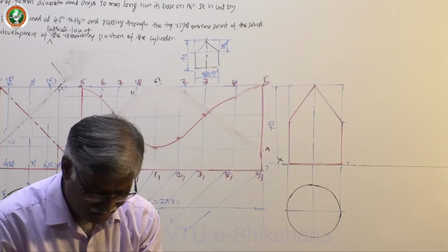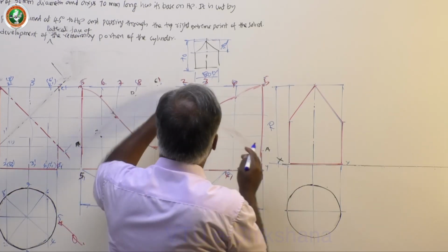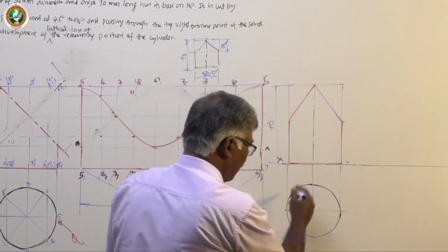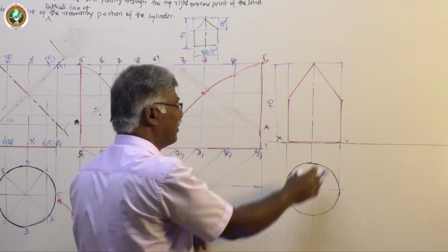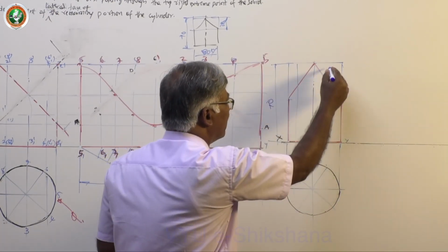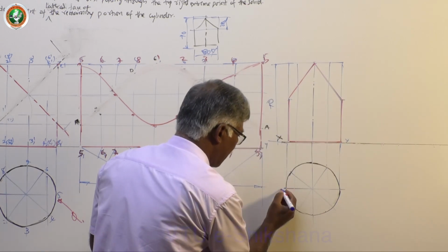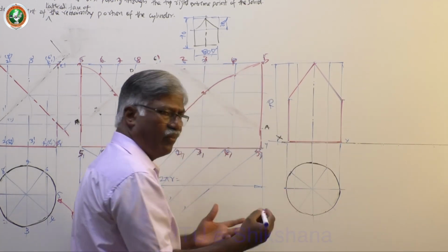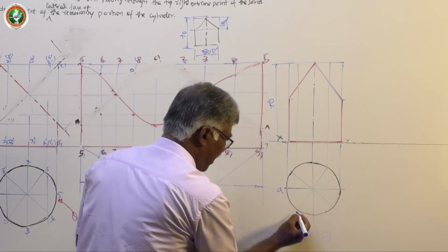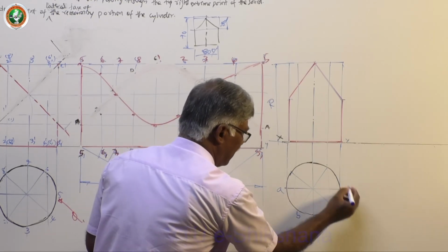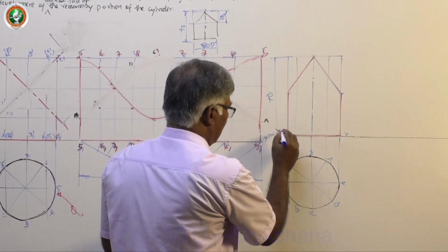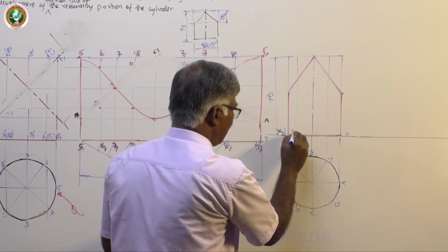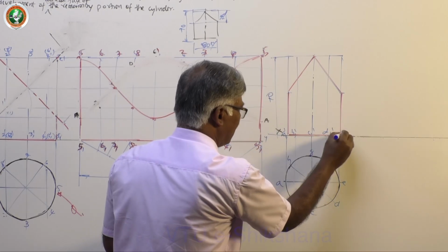Now, as usual, you have to draw a circle. Whenever they say 50 pi, you have to draw 50 diameter and then divide this into n equal parts because we have section planes. Then get this. Name these points. So let me even name A, B, C, D, no problem. So A, B, C, D, E, F, G, H. Okay, this is A dash, A1 dash, B1 dash, C1 dash, D1 dash, E1 dash.